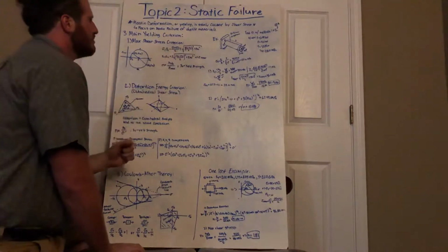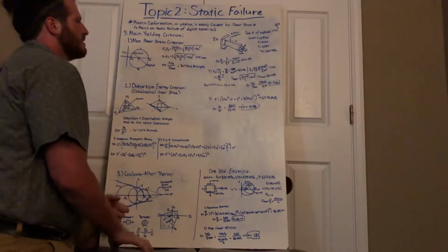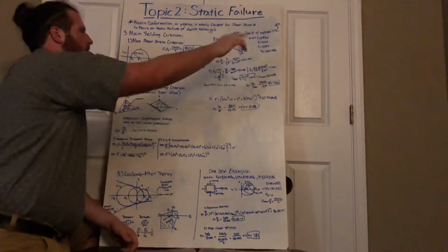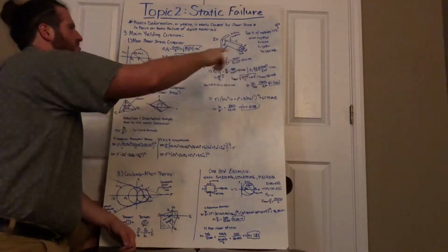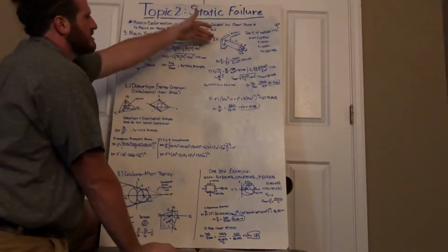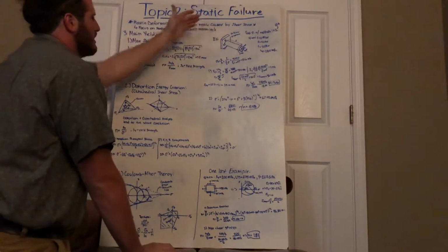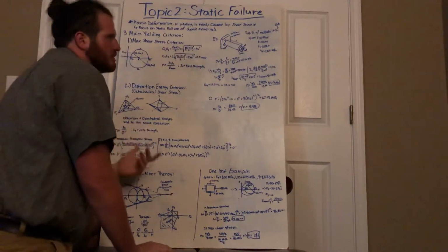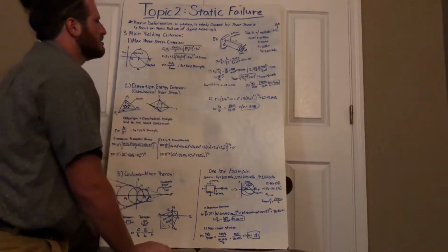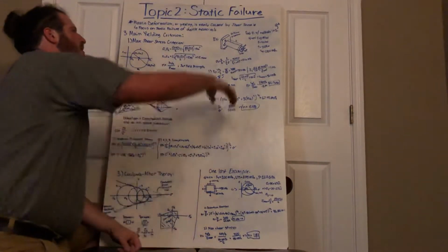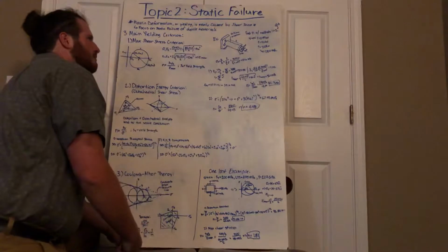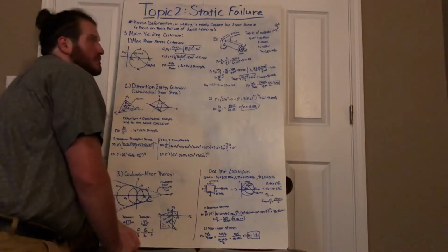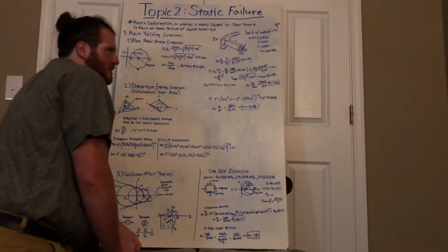Now let's look at it in an example. Here we have an example of a rod fixed at one base with forces applied in the x, y, and z directions, and also a torque applied to it. We're going to find n with this first method first. We are given that it has a diameter of 15 millimeters and a length of 100 millimeters, with this given force in this direction as 0.55 kilonewtons. The force in the x direction is 4 kilonewtons, and the torsion is 25 newton meters. And we're also given the yield strength is 280 megapascals.